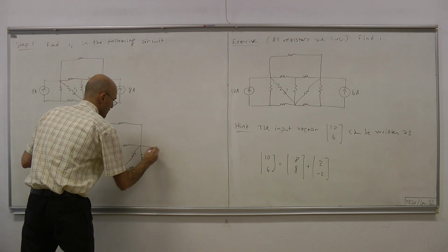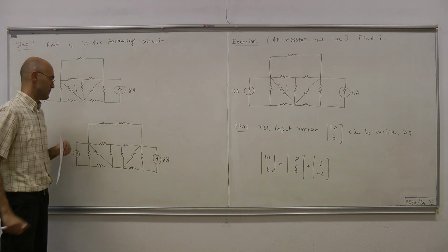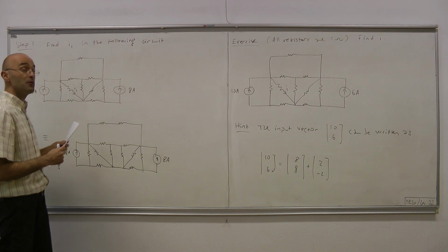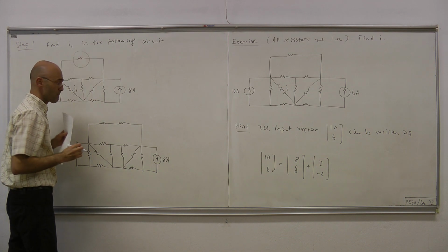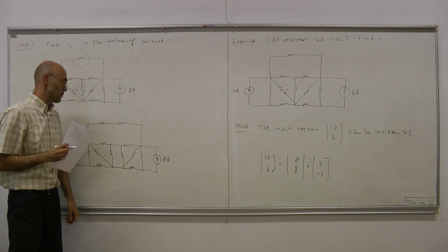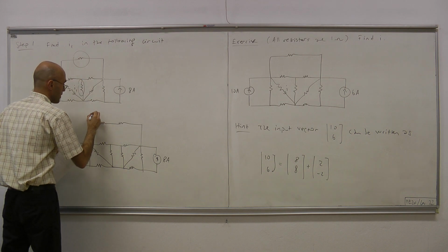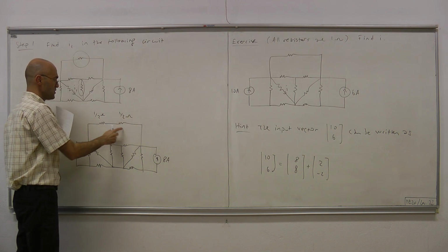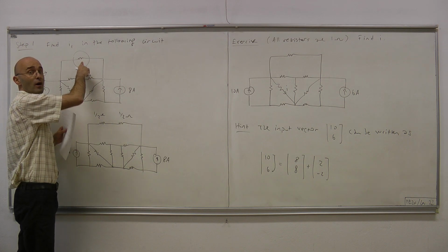And then, now, when you draw it like that, you have to be careful about the resistances. Okay. So what we modified is this thing and this, the in-between resistor. Now this was 1 ohm. Therefore, that 1 ohm can be written as 1/2 ohm and 1/2 ohm in series. Okay, this 1/2 plus 1/2, because they're in series, gives us 1 ohm.